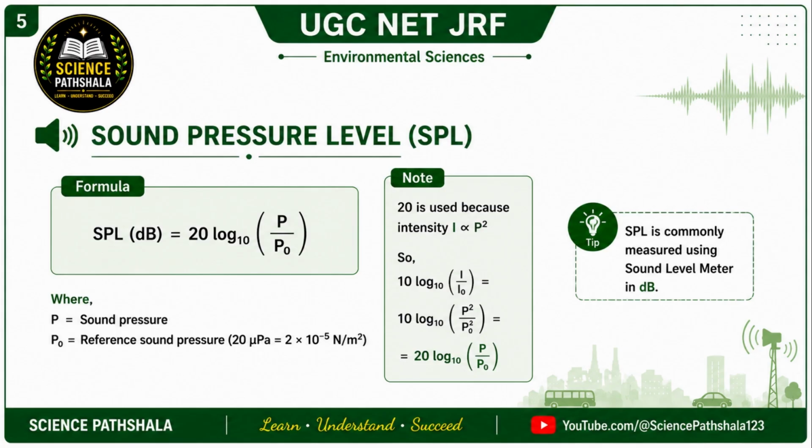Sound intensity is proportional to pressure squared. Therefore, when pressure terms are converted into logarithmic form, the multiplying factor becomes 20 instead of 10. SPL is commonly measured using a sound level meter and is widely used in environmental monitoring, occupational noise assessment, and industrial noise studies. So these were the basic concepts required before solving advanced numericals. Now in the next section, we will start solving important numerical problems step by step.